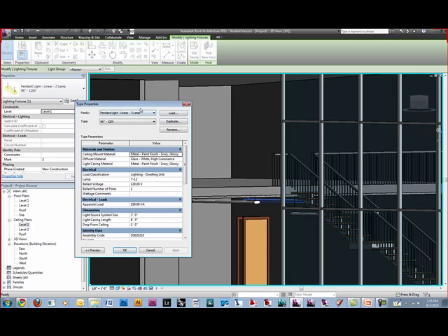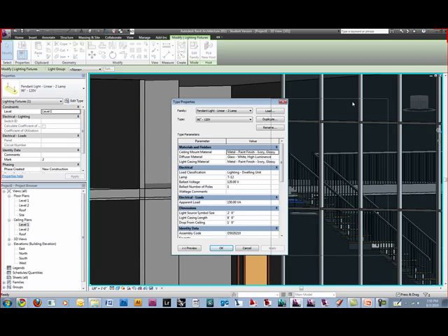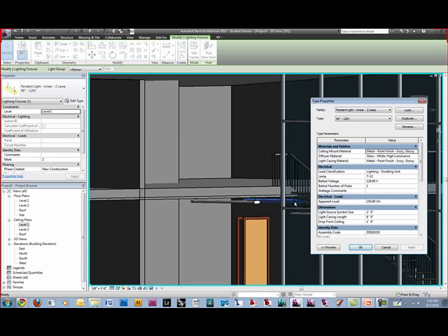If you want to change how far they hang down or their mounting heights, let's see if there's actually any of that. So if I go to edit type, I'm gonna try to set this where you can see it at the same time. It's under the 96 inch 120 volt. So if I wanted to change the height of those to drop from ceiling 2 foot instead of 1, I wouldn't have to duplicate it because I'm changing that, unless I'm going to use it somewhere else at a different height. At a different height, then I need to duplicate it.